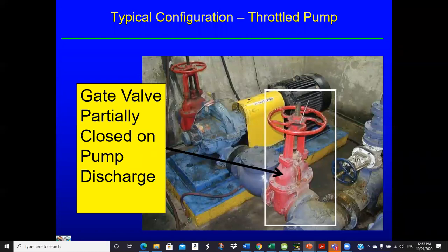So you look at the suction side stem and the discharge side stem, and if it's the same size valve, you can take your tape measure and say, this one is 8 inches sticking up here, this one is 4 inches. So that thing is about in the 50% position. Then the question is, at 50% on a gate valve, how much flow do you get?